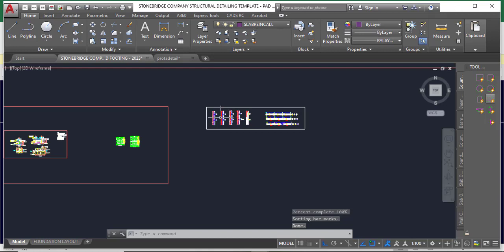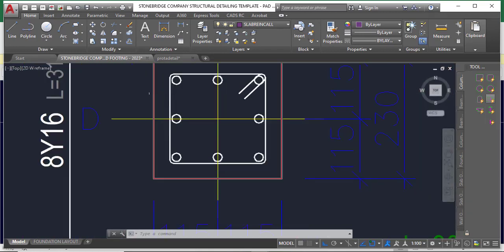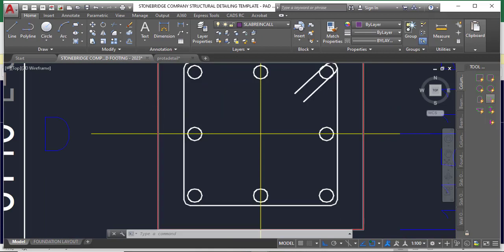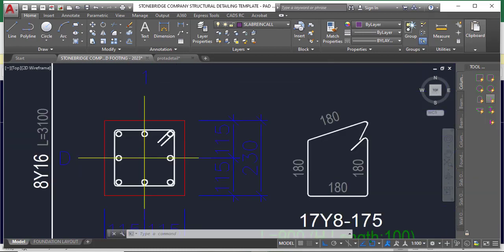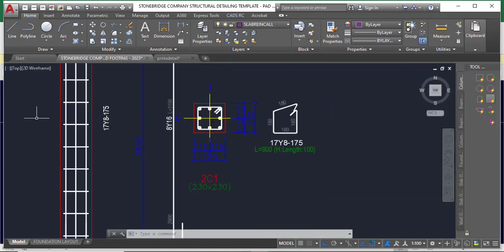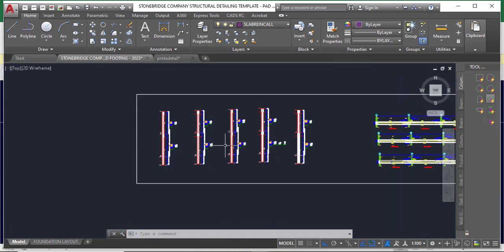All right. So now looking at this drawing, I have modified the drawing. If you look closely, you see that the white line is now thicker than the red line. It does not need to be abnormally thicker, but obviously you can see this white line is now thicker than the red line. So when you print this out, you will easily identify which is the reinforcement and which is the concrete boundary, even though it will appear as black and white on paper, but one will be thicker than the other. You can easily identify this. So this can be used on site.